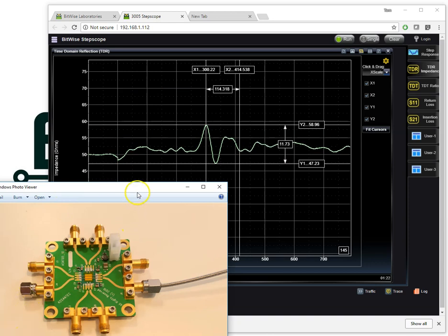The fast updating speeds that we're seeing here include already averaged waveforms. So there's no need to turn on large numbers of averaging, something that we used to always have to do using sampling oscilloscopes to get fine measurements, because of the way this waveform is sampled.